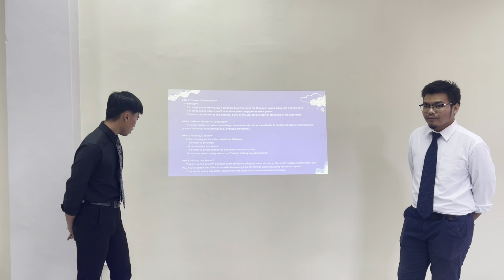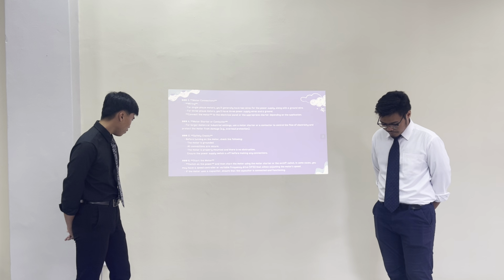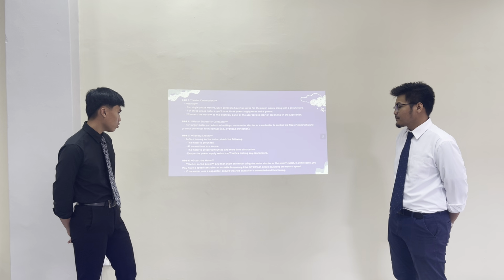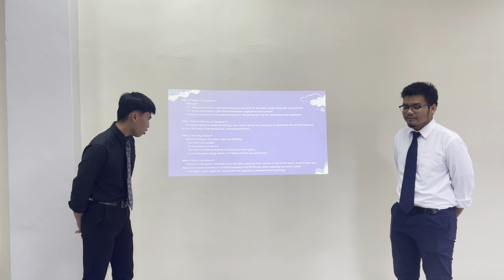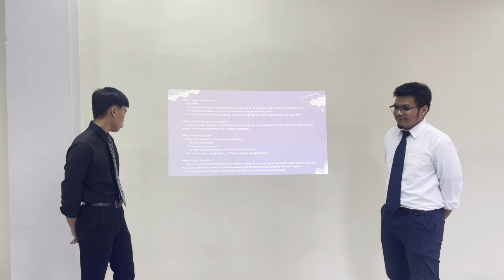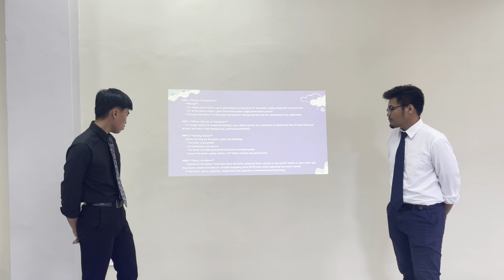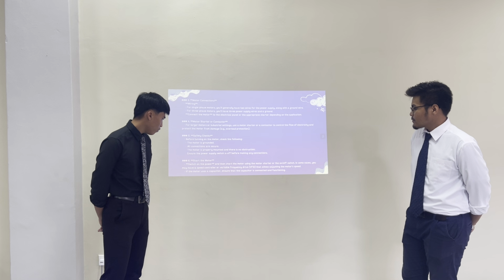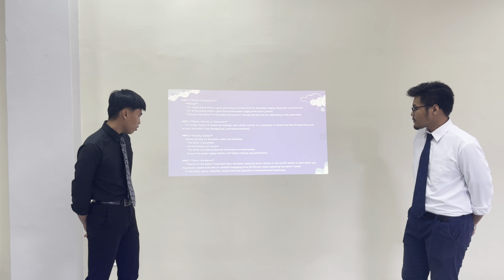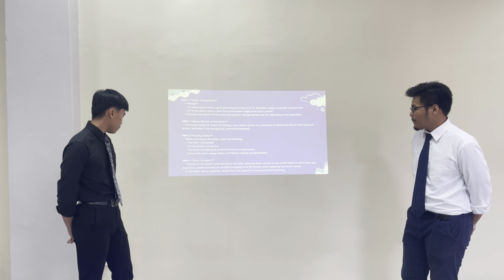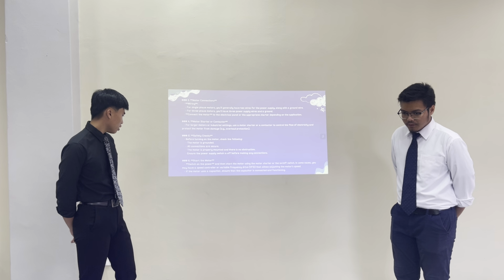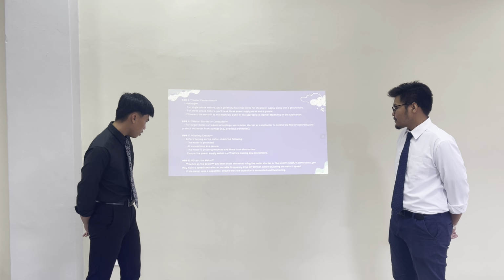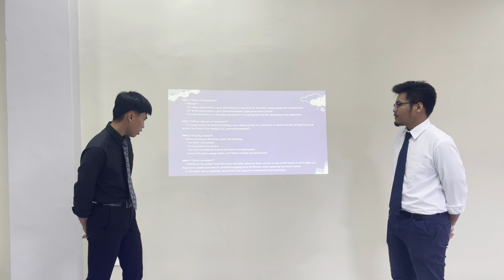6. Start the motor. Switch on the power and then start the motor using the motor starter or the on-off switch. In some cases, you may use speed control, such as a variable frequency drive or a brake handle, for adjusting the motor speed. If the motor uses a capacitor, ensure that the capacitor is connected and functioning. Next,